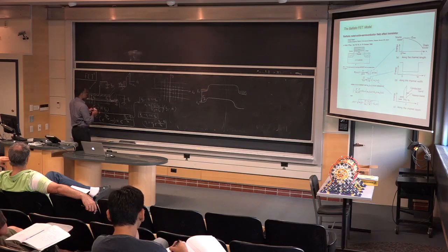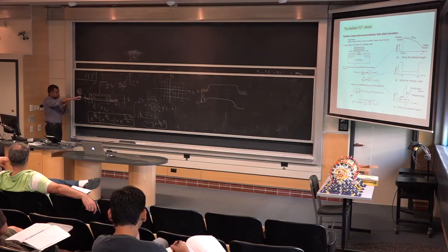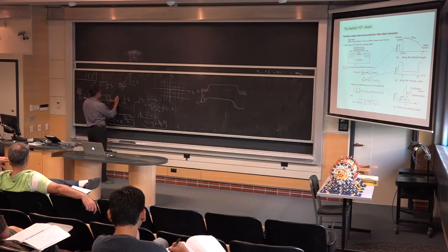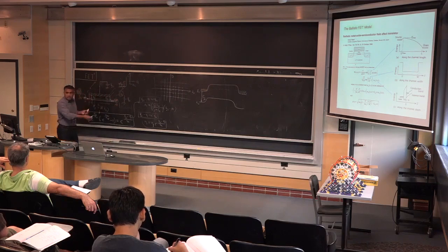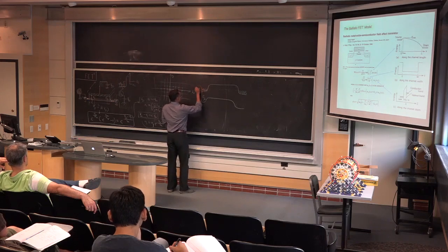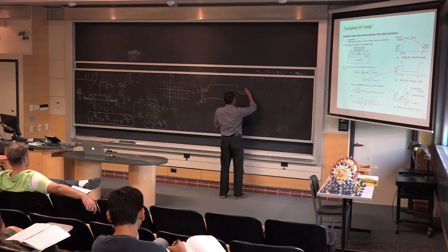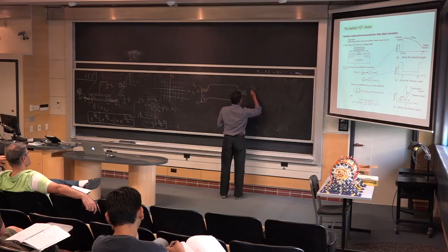Similarly, this side. Wait, I already screwed up. Okay, no, colors should be right. The Fermi level of the source is whatever this metal is sitting at. It has a unique Fermi level, and that is it. Similarly, here the drain has a Fermi level of the drain, and they need not be equal, but when they're shorted, they're obviously equal. Meaning there is no potential difference between them, so they're equal. This point here is E Fermi of the source, and the top here is E Fermi of the drain. That's what we're saying.